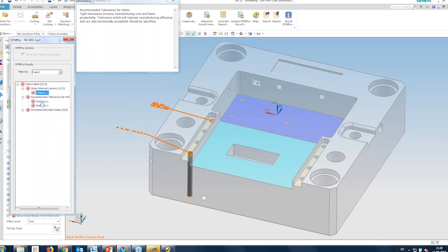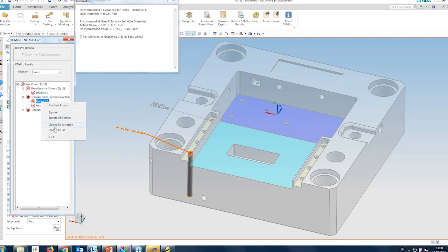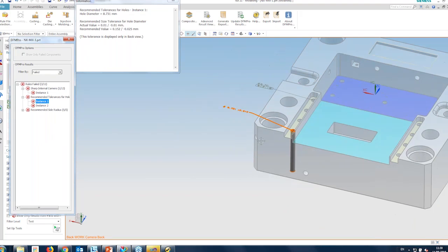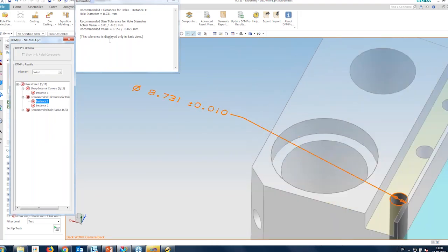And then the second is this pocket, which I have again modified. So if you see here, initially there were 3 instances, and now I have just 1 instance remaining to eliminate the sharp corners from. And again, as I mentioned earlier, you have a choice to discuss this with your manufacturing teams by generating reports, or you can, based on your understanding of the design as well as the functional requirements, eliminate this particular sharp corner quickly based on the values that are supposed to be added.